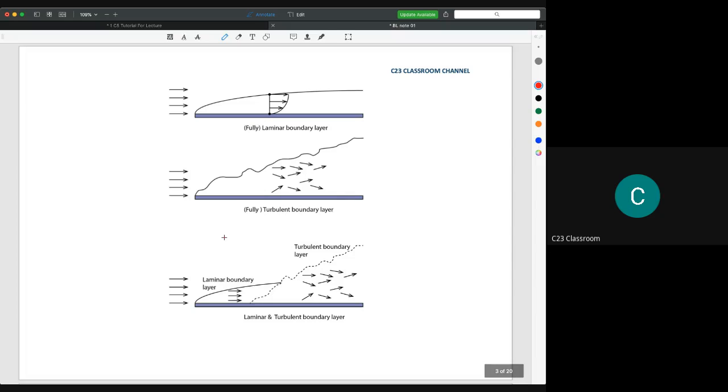In this topic, we will also discuss the difficulties of the turbulent boundary layer. If the boundary layer is 100% laminar like this, we could use the von Karman solution and also the Blasius exact solution. If the speed is too high, we could assume that the whole boundary layer is in a turbulent condition, so we could use the idea of turbulent boundary layers.